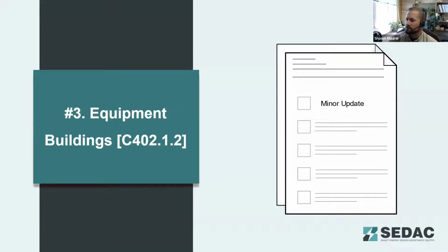Okay, I'll go ahead and share those results. All right, excellent. People did pick up that grain silos, being agriculture, would not be required to comply with the Illinois Energy Conservation Code. So good job on that. And most people did pick up on the two that are required for this certificate: envelope R values and fenestration performance. The third item was air tightness, but that would not be HVAC performance, and lighting power density is not on there either. So overall, pretty good on that.